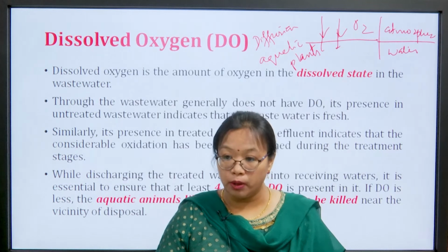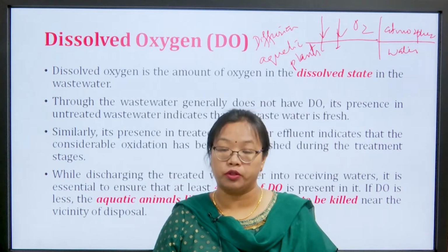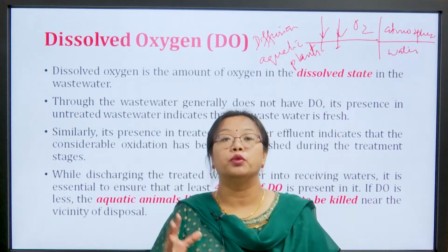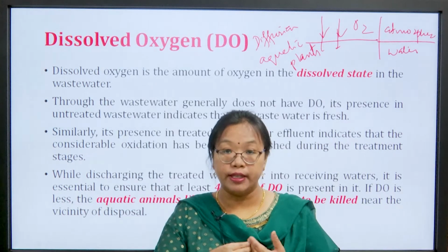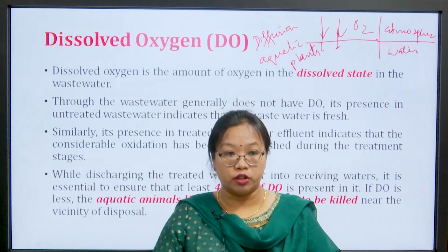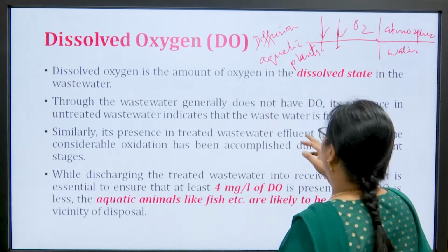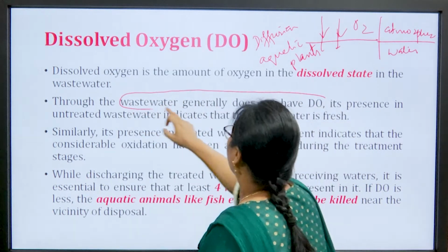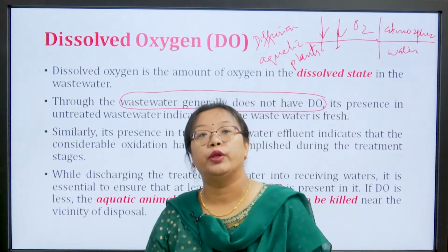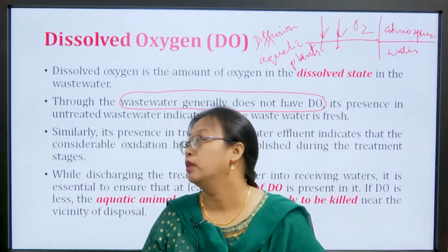But when we talk about wastewater, when it is fresh, there will be dissolved oxygen, but with the passage of time, that oxygen will be used up to oxidize the organic matter present, and after a certain time all the oxygen will be used up, right. That is the reason why you do not expect any DO in wastewater, right. But if, say for example, the wastewater is fresh, then you expect certain DO.